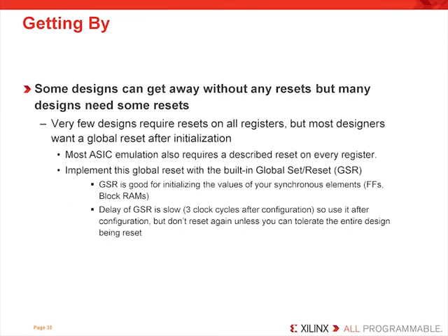We have found that actually only some designers need a global reset in their design, especially since the FPGA automatically performs a global reset as part of the configuration process. But as I mentioned, many ASIC designers find this essential for resetting their system extra times. So your way of resetting everything is with the startup component in that case.